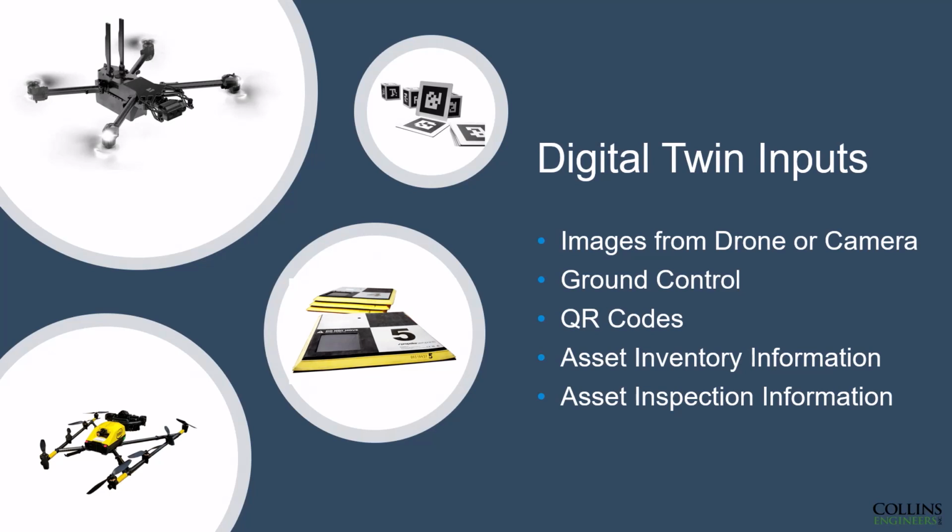This is the first step. Obviously, you got to capture the data. There are several different methods. You can do photogrammetry using a camera. You can do LiDAR. What we've found is most efficient is using a camera to capture photographs and then using a photogrammetry post-processing software. The LiDAR imaging is a little bit more expensive. Requires a little bit more post-processing on our end. So really what we've been digging into is the photogrammetry aspect.